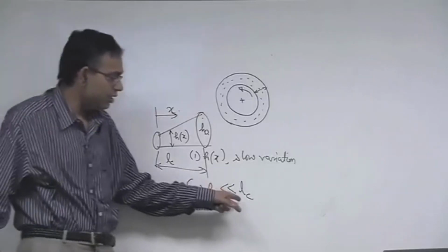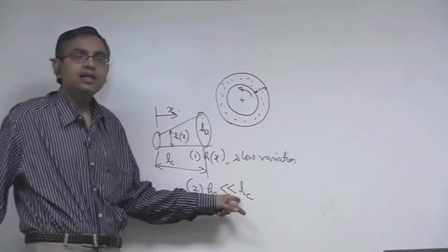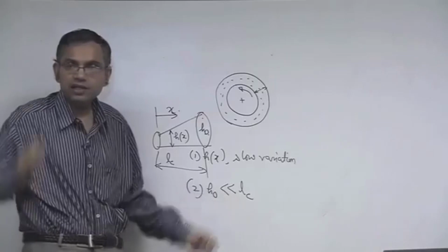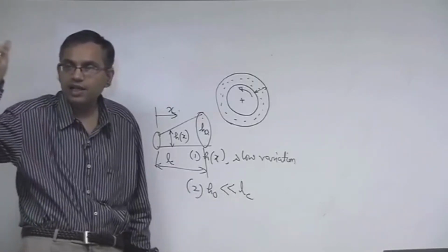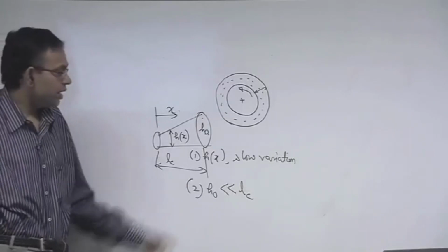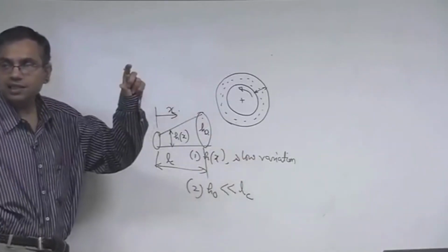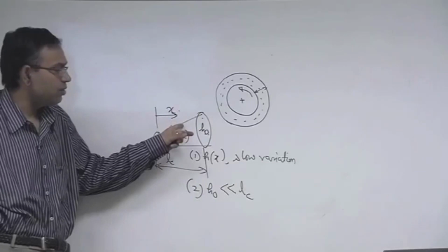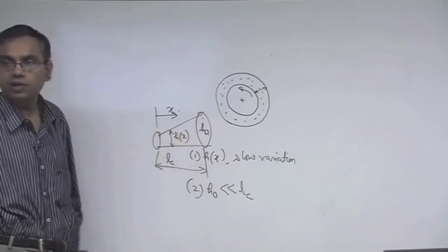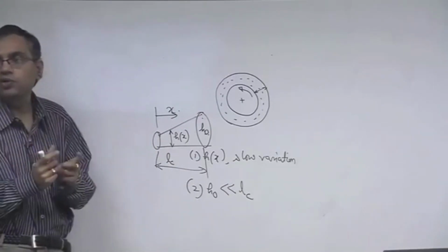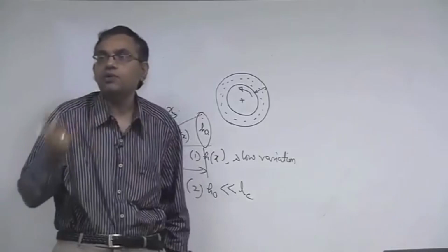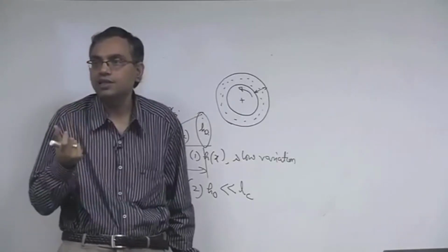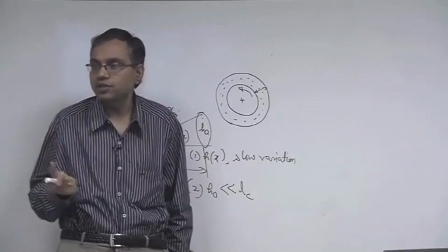This is a condition that we already discussed in detail in our discussions on low Reynolds number hydrodynamics. We have considered that the y length scale is significantly less than the x length scale, but we have not considered any variation in the flow passage. Nor have we made a general discussion for the scenario when one of the boundaries has a relative motion with respect to the other boundary. So, when you take all these in purview, the general theory developed for this is known as lubrication theory, and the name comes from its applications in the context of bearings in tribology.